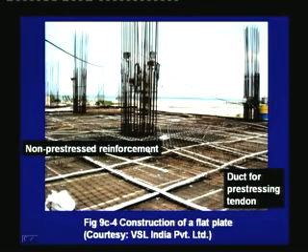This is the construction of a prestressed flat plate. We can notice that the silver ducts are the ducts for the prestressing tendons, and they have been given an appropriate profile for the placing of the tendons, which is based on the design of the flat slab.